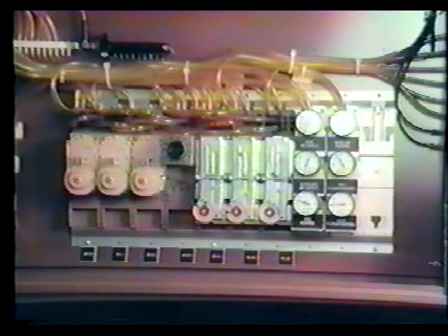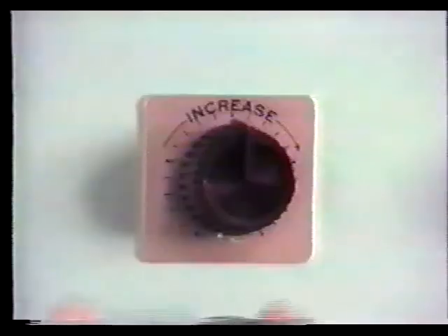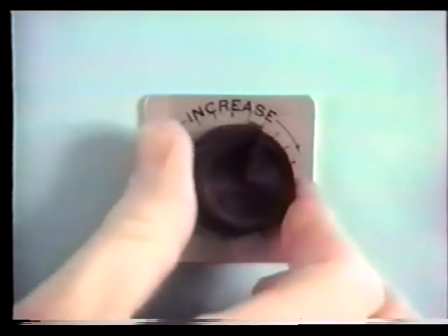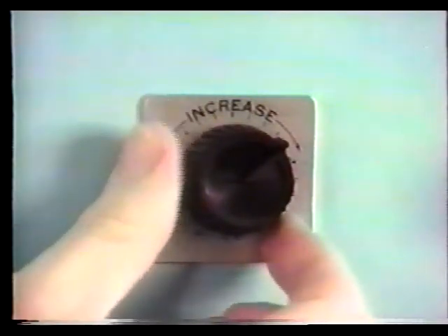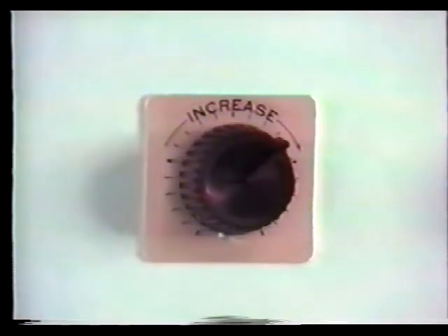An example for this type of application might be a panel containing receiver controllers with gauge readouts piped to a central control location or operating console. In response to a change in the system requirements, a remote adjustment could be made from a central control panel, raising or lowering the set point of the receiver controller by varying the 3 to 15 PSIG input to the CPA port on the receiver controller.